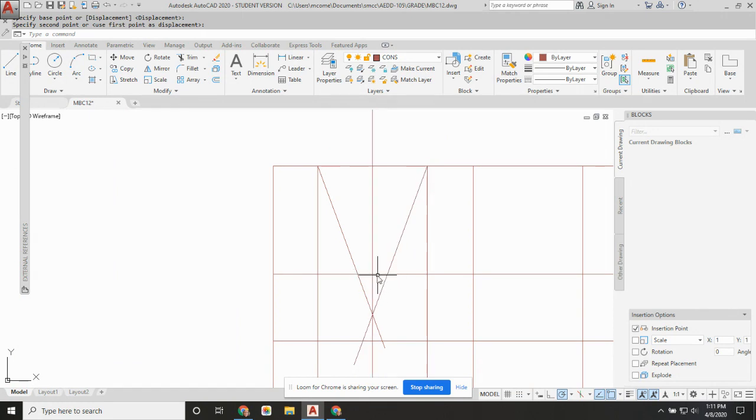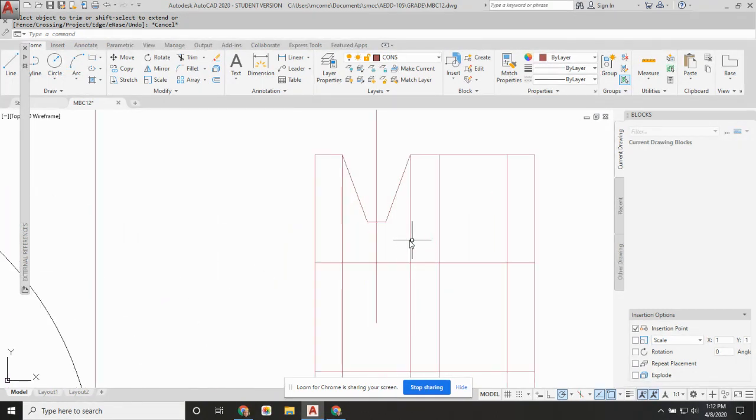And then the resulting width of the bottom of this V is where those lines cross this line that has the depth of 0.62. So if I trim to that line and then trim to the edge of the V pattern that I have here, that's the shape we're looking at right there. And there's that V. Okay, now once you've solved it in one location, then you can pick it up and copy it at another. So let me show you another approach.